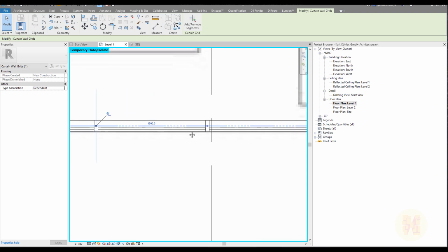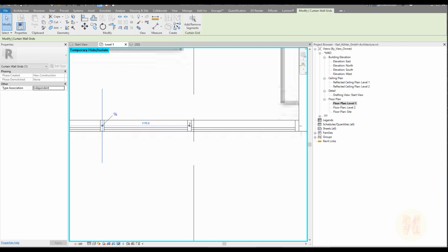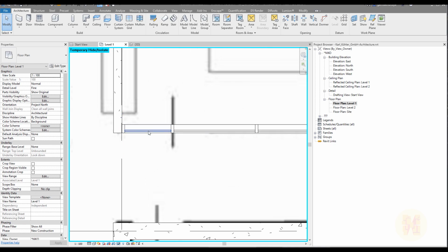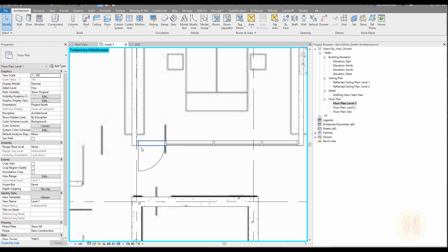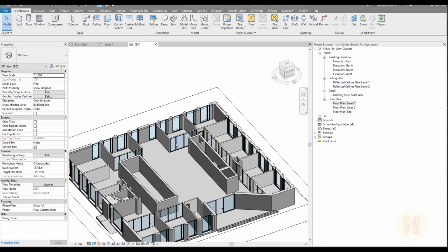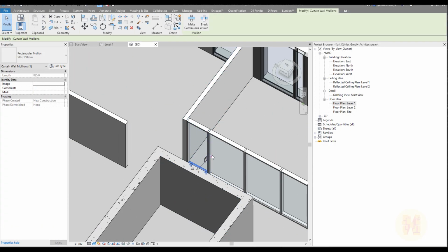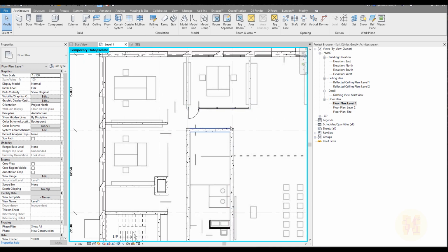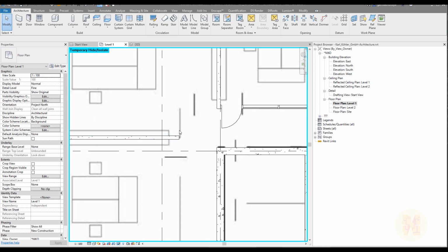Oh, as you can see, I didn't unpin it. Now I did unpin it first, and after that changed the dimension. Okay. Select the panel, door. Yeah, it will be opening on this side. 3D. Let's select it, unpin it, delete. Okay, here we have again the same thing as here, but here we can actually place our curtain wall,